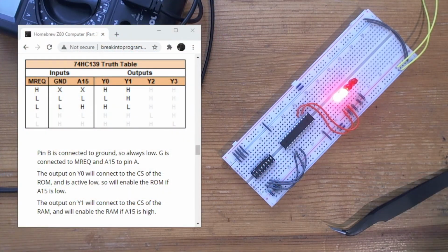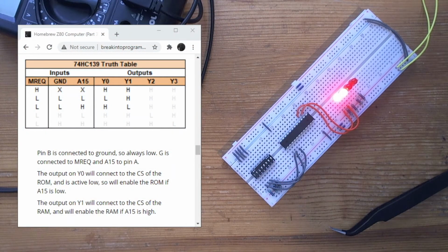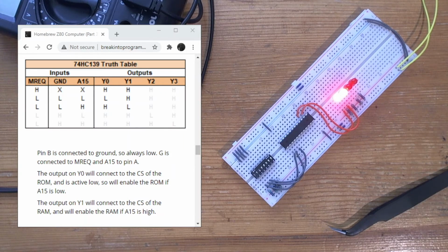So finally, we have some success. We have blinking lights. Well, lights. It turned out that the verify fail that I had earlier wasn't a false alert. It was simply that the device wasn't being programmed by my EPROM programmer.